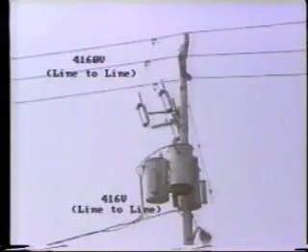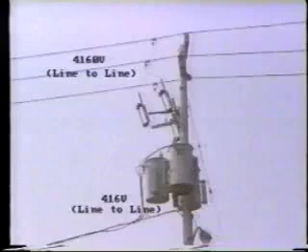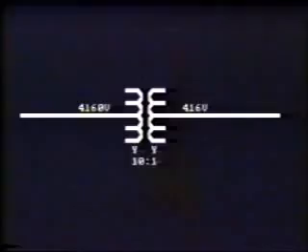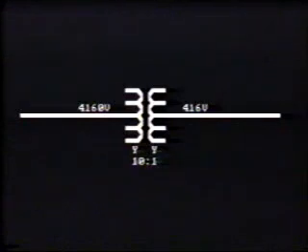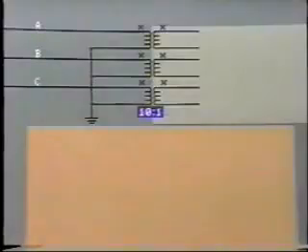Polarity is extremely important when it comes to connecting up three-phase transformers. Let's consider the case of a distribution transformer, say 4,160 volt primary to 416 volt secondary, connected Y-Y. This could be a three-phase unit or three separate single-phase transformers, as shown here. On a single line diagram, this arrangement would probably be shown like this, with the Y-Y symbols indicating the connections. More detail will be shown on the circuit diagram.